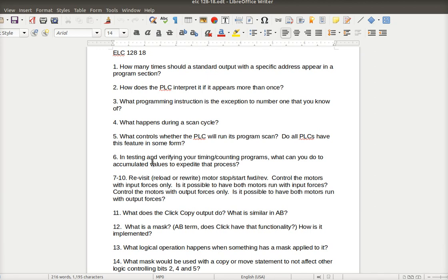And I tend to be of the position where you should not use a force. My background has been around equipment with people running, so the danger I see with input forces is an operator's used to pushing a button and the machine stops. Well, if you force that button in such a way that it no longer works when the operator presses it, you are creating a potential safety issue. So I would not do it.